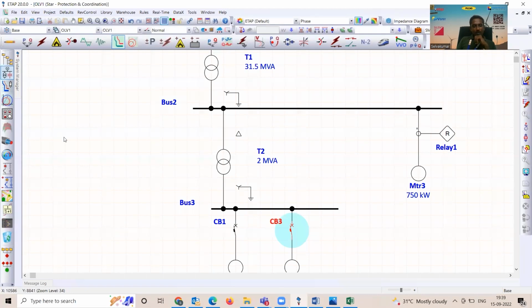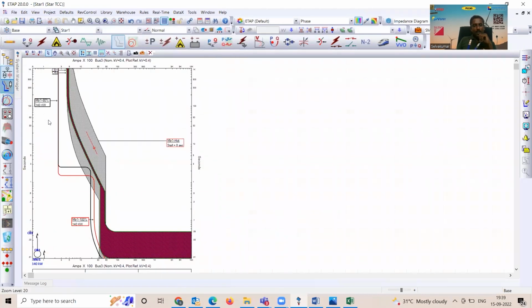When I put up a graph, I drew the motor starting characteristics like this. But this starting characteristic is applicable for a direct online starter, not for a soft starter or a variable frequency drive. If you have a soft starter or a variable frequency drive, how do you draw these characteristics? This is the starting characteristic of the given motor with direct online start.